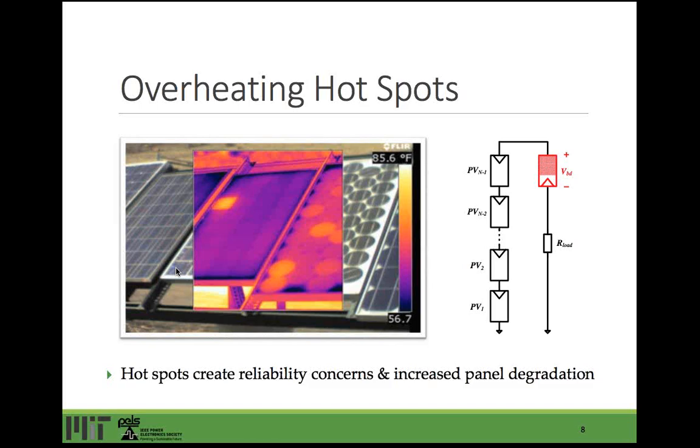And because of the previous two problems, installation sites for solar PV must be very carefully screened and selected. And this results in a constrained feasible market size. So you can see on the house on the left, the solar installation is usually not recommended due to heavy shading problems because it's got trees on all three sides of the house. And on the house on the right, although a solar installation can be built, it has to be undersized to avoid shading and mismatch problem on the trees on the left.